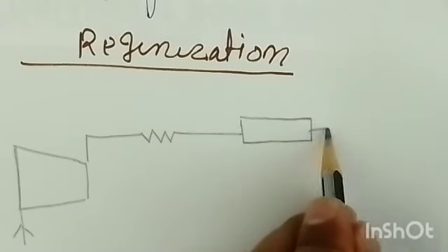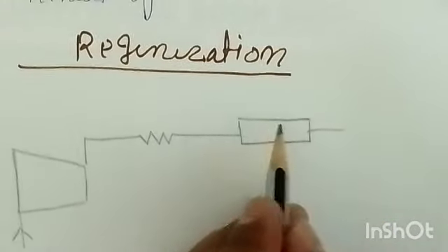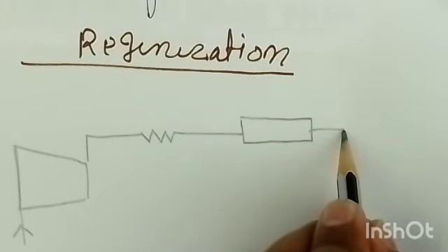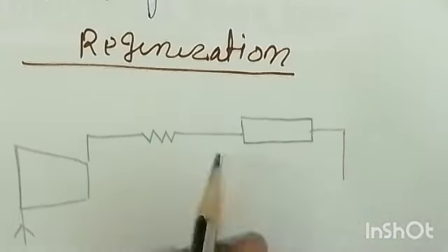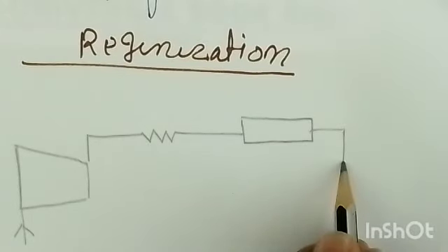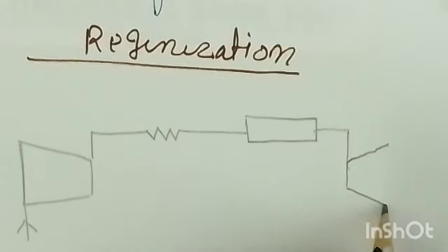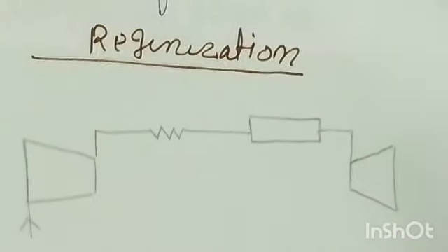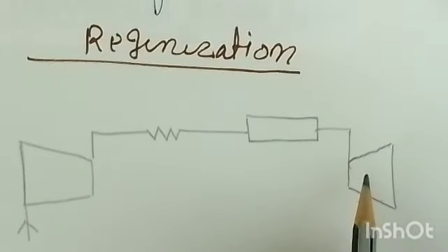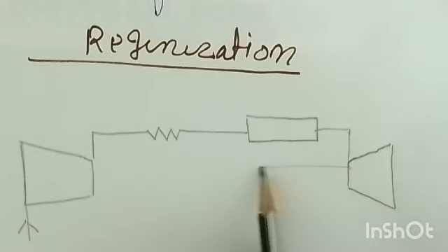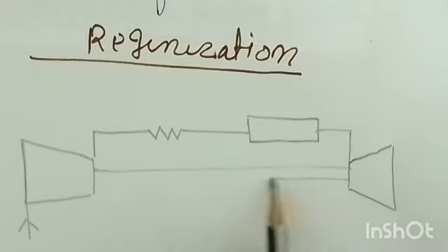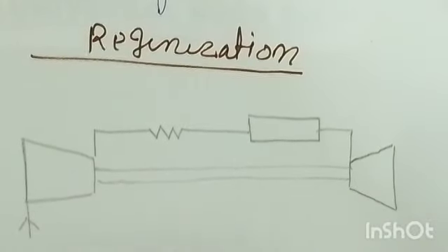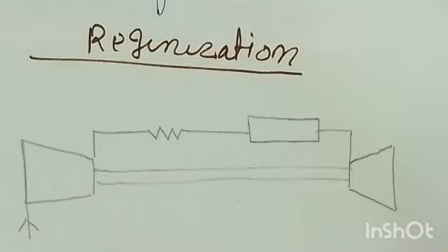After that, heat is supplied to the combustion chamber, and then the hot gases will enter into the turbine. In the turbine the expansion takes place, that is reversible adiabatic expansion. Then work is produced, and some of the work is supplied to the compressor to run the machine, and the remaining work is utilized for power production. And after expansion the gases have to be released.